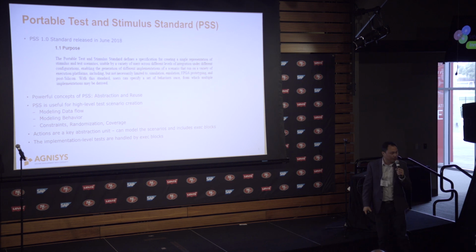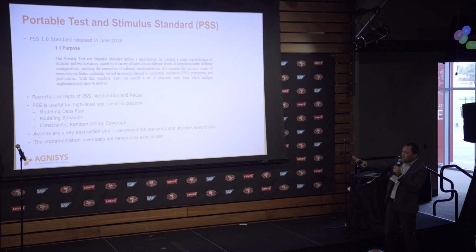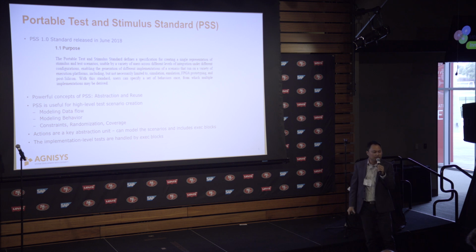PSS is very useful for creating high-level test scenarios. Within PSS, there are what are called actions, and those are key abstraction units. Inside actions are exec blocks, and the exec blocks are the blocks where the implementation level tests are defined.